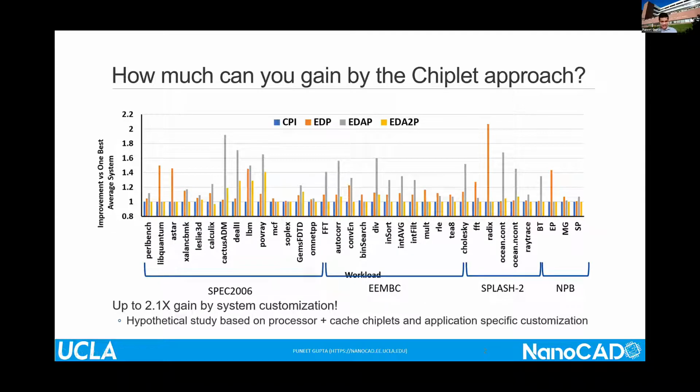So let's start. I'll start the talk with a result plot itself. This is some work we had done a couple of years back of just looking at a relatively simple chiplet-based system where you have a processor and its last level cache, SRAM, separated into chiplets. And what we were trying to look at is if I have multiple product lines of this generic processor, each serving a different market segment, can I share these chiplets to reduce the total chiplet ecosystem costs? And if I'm able to do this, what do I gain?